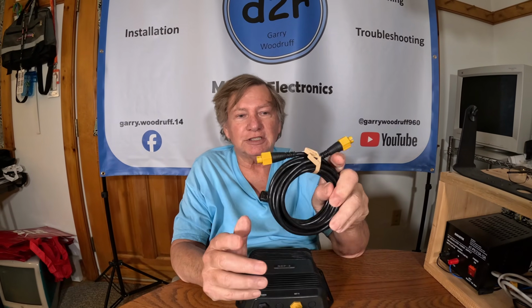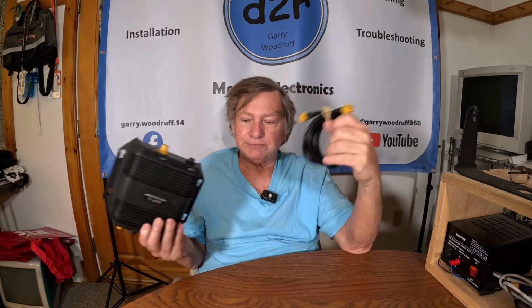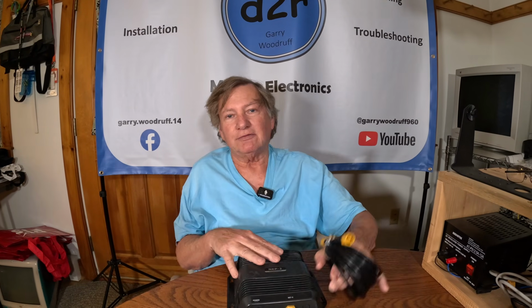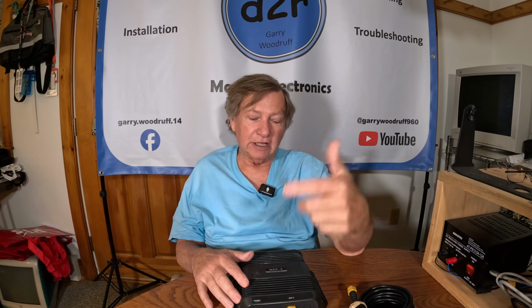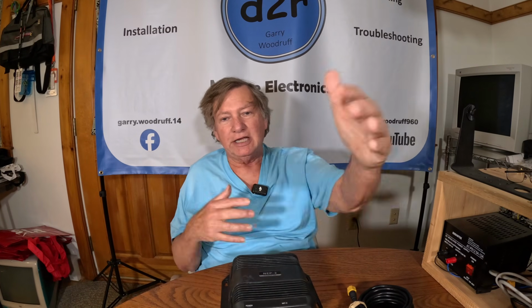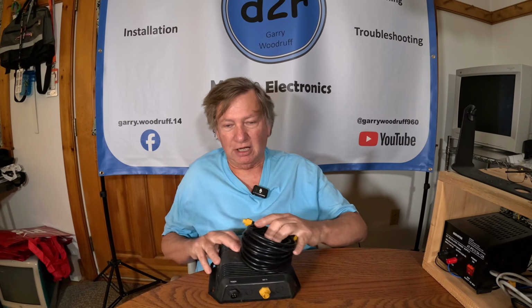So hooking up Ethernet is fairly simple. Hardware is fairly simple. You basically have a network hub and you have network cables. Very, very simple. You have to plan ahead. For example, when I did that Elite FS boat and I added an active target module, I had to add the NEP2 to it so that I could hook up 3 devices, because Elite FSs have 1 network port, okay? And I needed 3. I needed 2 network ports on 1 unit, and then I needed another one, okay? And the idea was to connect the 2 units together and connect the active target into the network. So the hub is the way to go. All right, so that's in a nutshell about how you connect Ethernet.